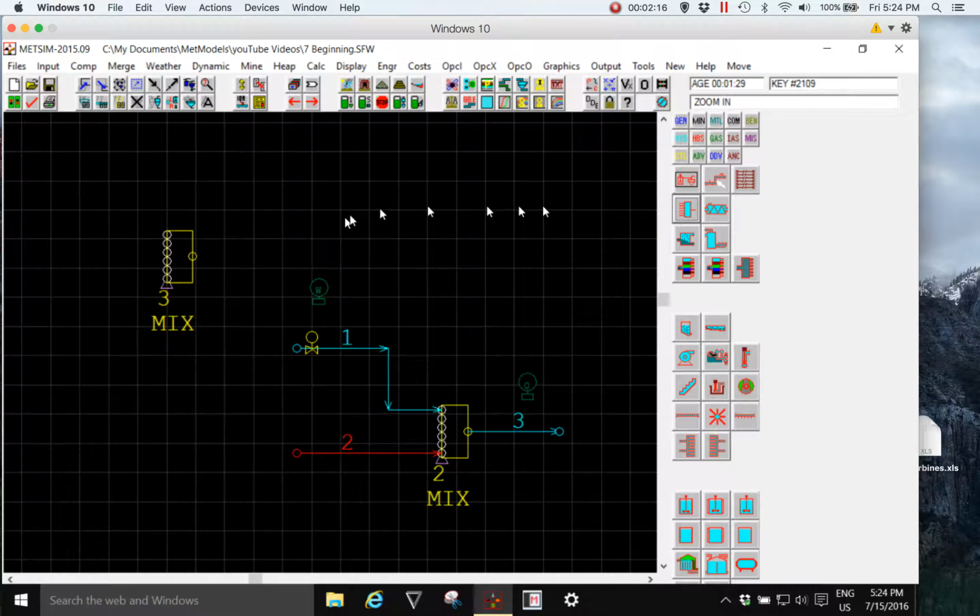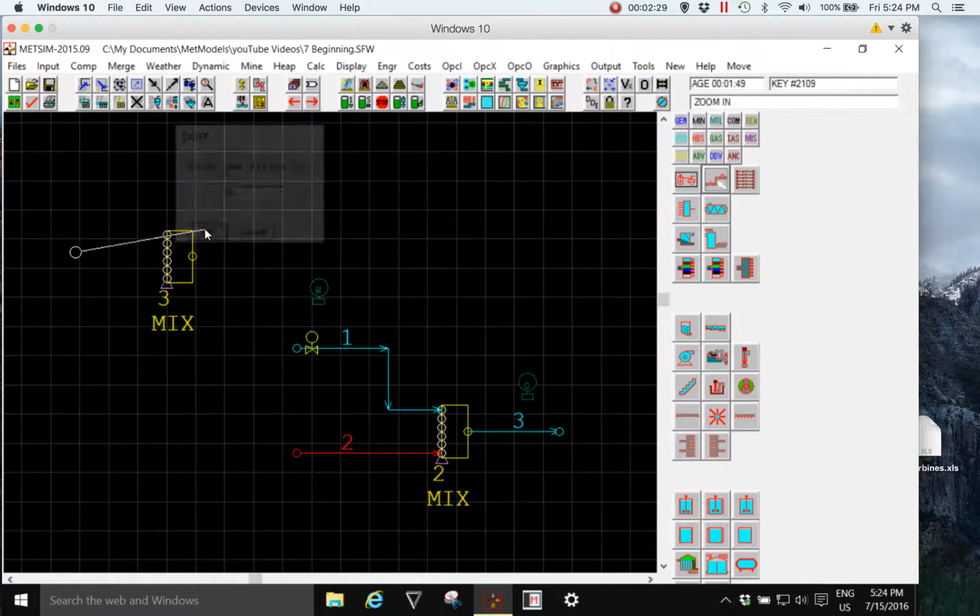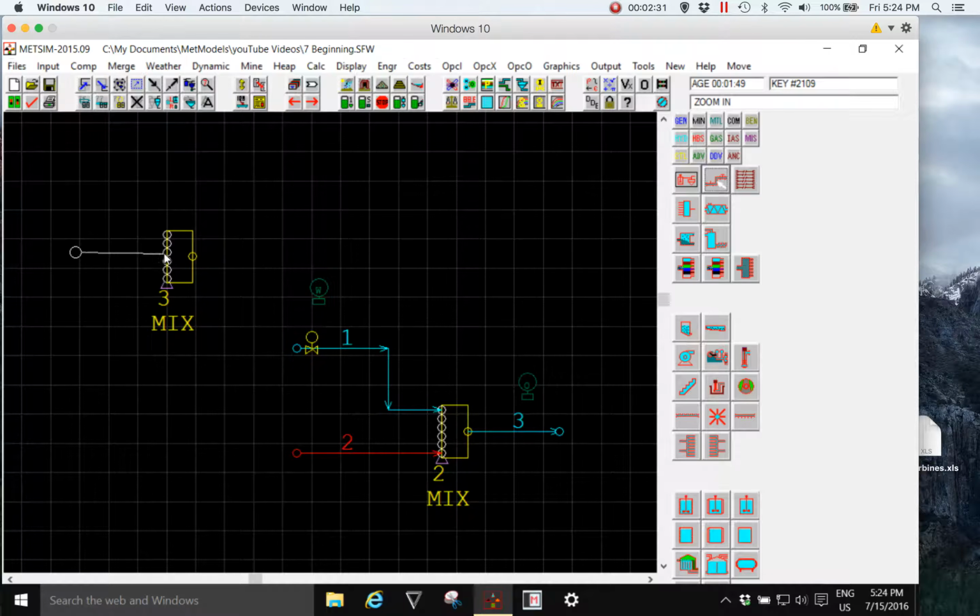I now activate the stream or pipe construction unit operation model and left click to commence the construction of a stream. Select the suggested default stream number and carefully left click again at a valid inlet connection point on the unit operation.